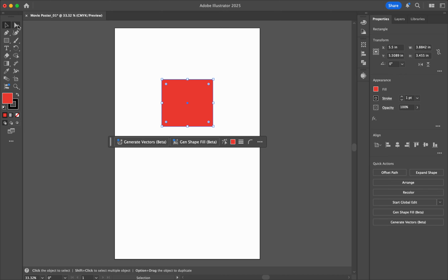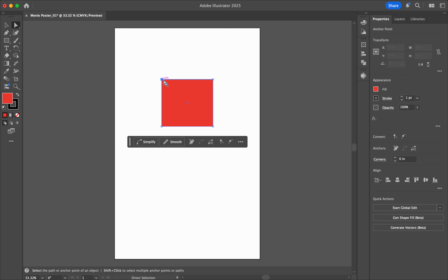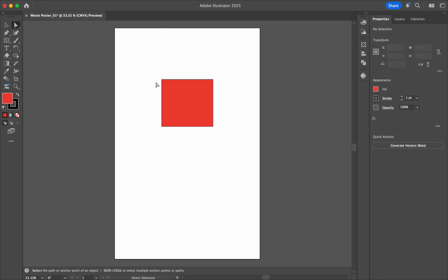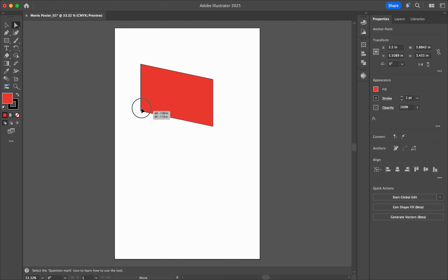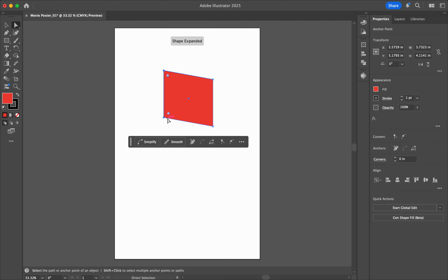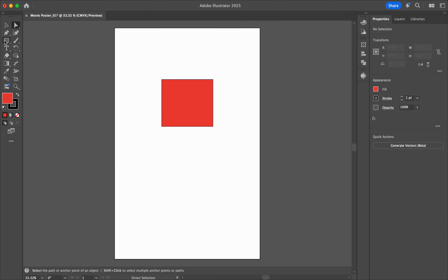The white arrow selects one anchor point, so one of these points to move around. Say I want to select more than one thing, whether that be more than one object, more than one anchor point. I'm going to click the first one first, then I'm going to click Shift, and then click another one. And now I've got two anchor points that I'm moving. Make sense? All right.